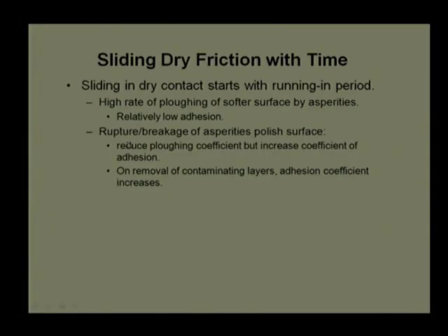And if this process continues, there will be some rupture, some breakage of the asperities. Due to that there will be a reduction in the plowing effect, or the coefficient of plowing will decrease, but due to this there will be an increase in coefficient of friction due to adhesion.